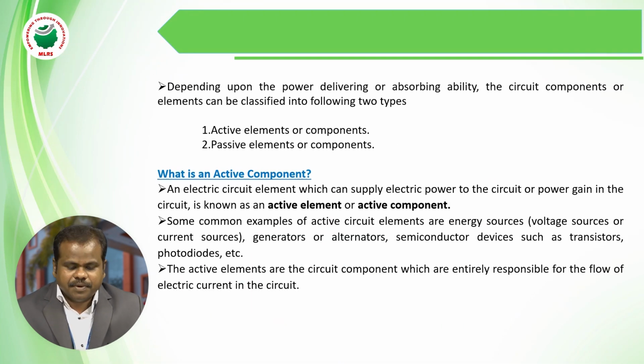Next, the second part of the classification is active element and passive element. So based on the power delivering or absorbing capability, the elements can be classified as active elements or passive elements. So coming to the first one, active element. An active element is such an element which is able to deliver energy to the circuit. That is, in an electrical circuit, if an element can supply electric power to the circuit or power gain in the circuit, it is known as an active element.